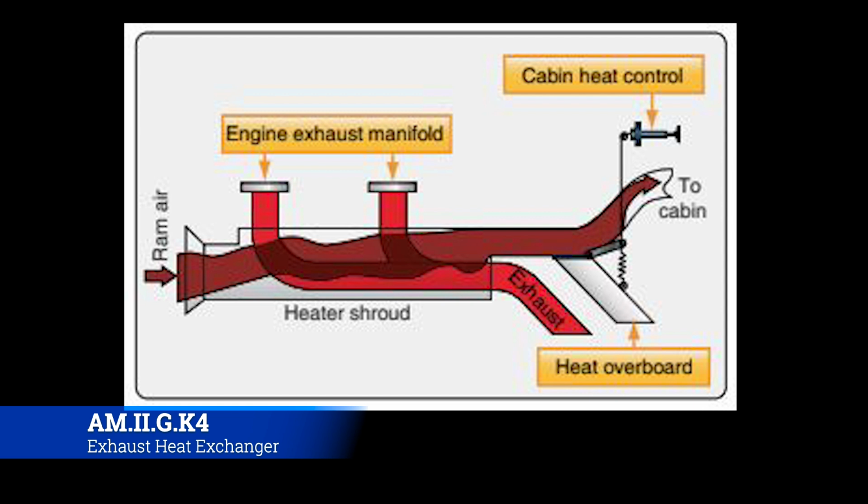You just have to be really aware of the status of your exhaust manifold, flanges, all that good stuff, or else you could actually give somebody carbon monoxide poisoning. And we've already learned about carbon monoxide poisoning in our fire systems class, but this goes to show you the importance of carbon monoxide detectors inside of the cockpit, especially if you can position it so they're close to where the heater ports are. That's what's going to give you the earliest indication that there's carbon monoxide coming into the cabin.